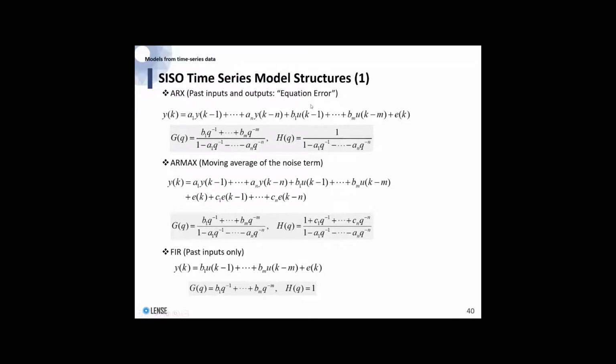Now, when you have this deterministic input, like a manipulated input, then it enters like this. Normally, without these U terms, it's called an autoregressive model. But because you have these deterministic inputs in addition, you're trying to combine the trend model with the causal model. That is called the ARX model. So X here stands for extra input.